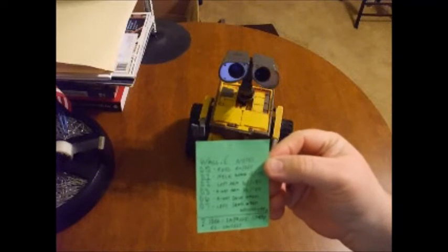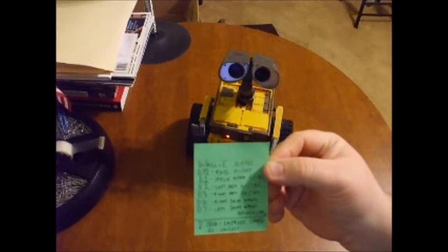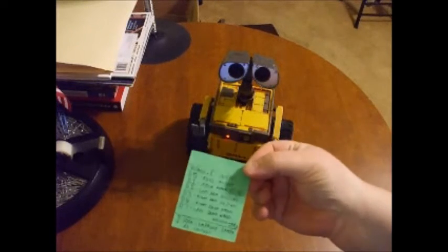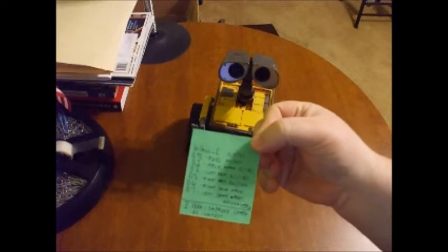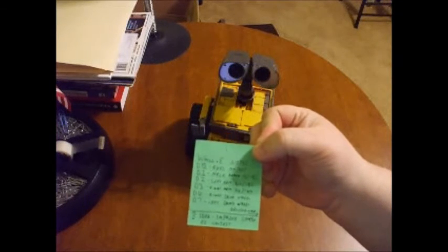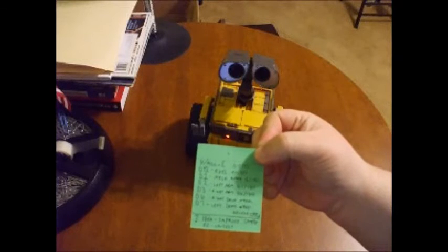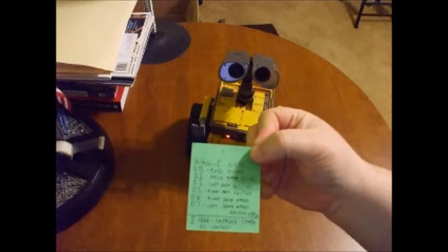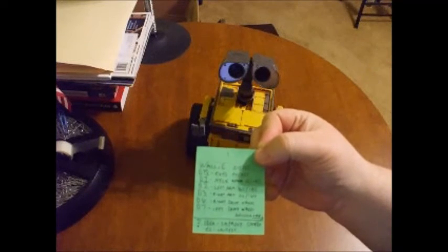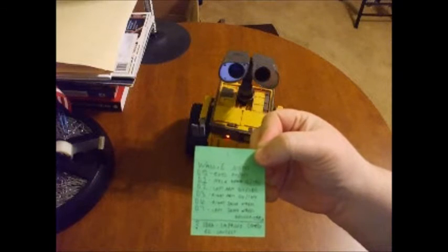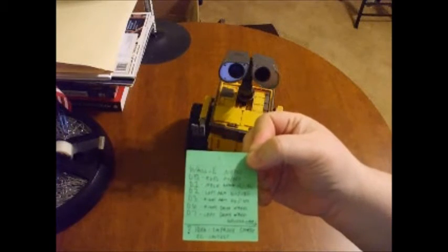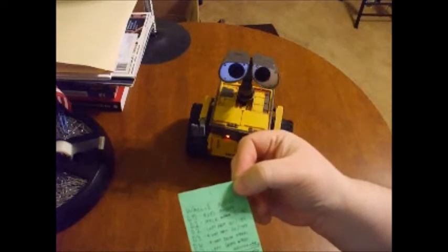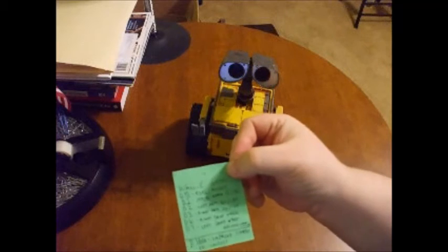D0 is his eyes, D1 is the neck, D2 is left arm, and I'm not sure if you can see my handwriting there, but I also have values for the maximum servo range of the left arm and right arm. So his right arm is D3, his right drive motor should be D6, and his left drive servo should be D7. And then I made a note for myself that I wanted to do some kind of comedy routine for him.